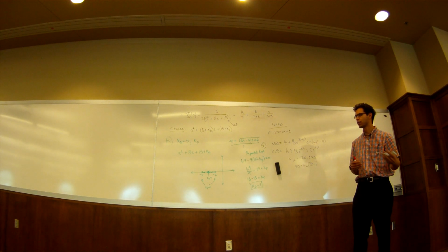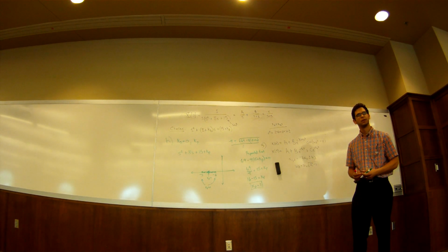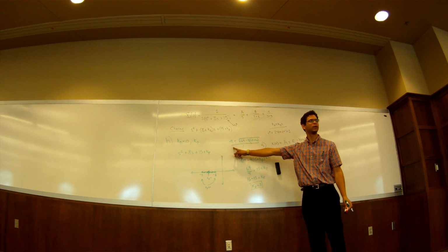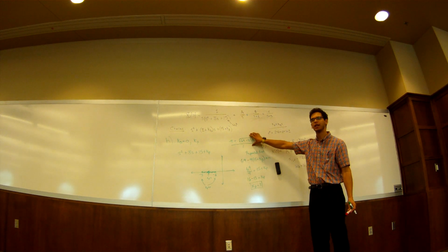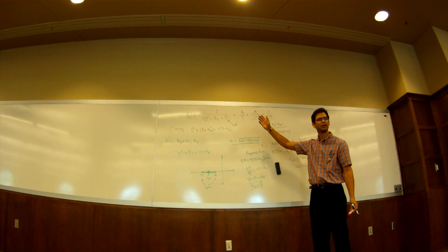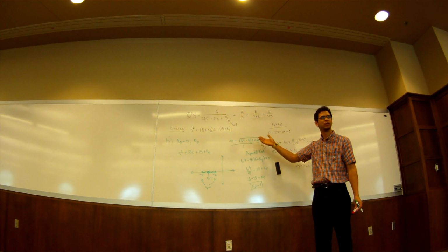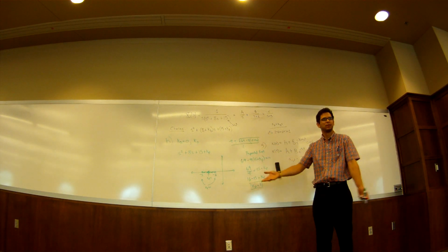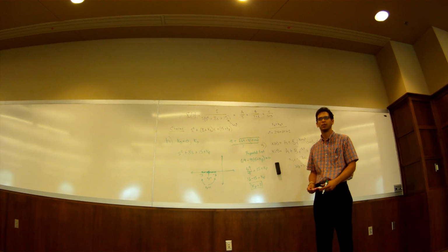If I make Kp greater than 1, what happens? They're just going to go straight up and down. How do you know it's straight up and down and not curved? Because the real side of your root stays the same. The real side of the root is always going to be -4, right? Do you guys see that? Yeah. So if you change this, and this goes imaginary, you're just going to go straight up, okay? If you want to do it the long way, what could you do? If you want to make sure, what could you do? Plug in Kp equals something greater than 1. Give me a number greater than 1.